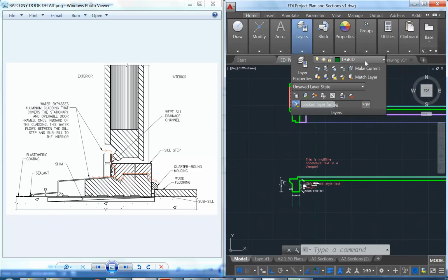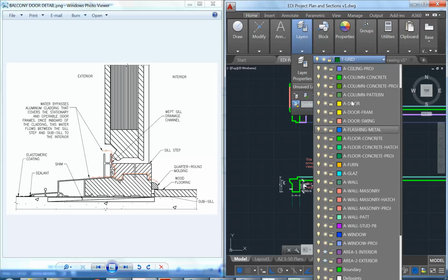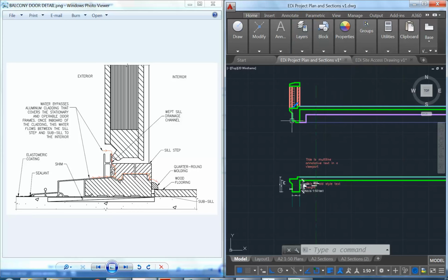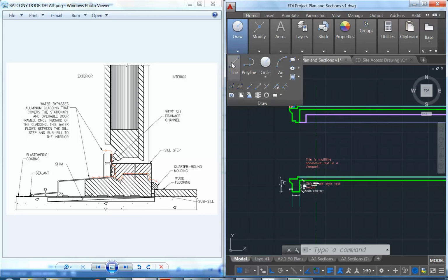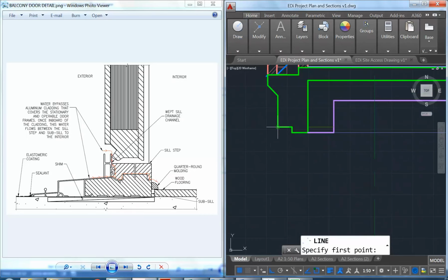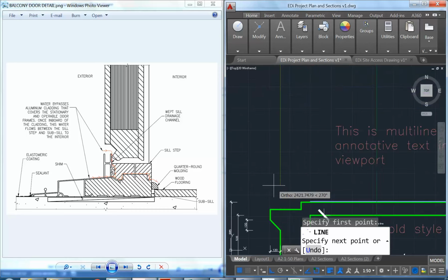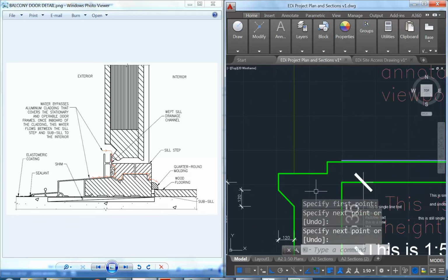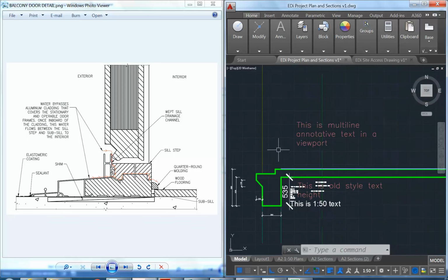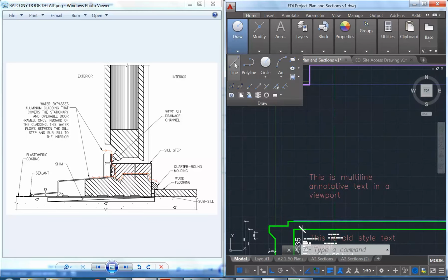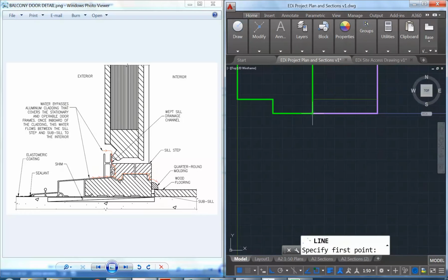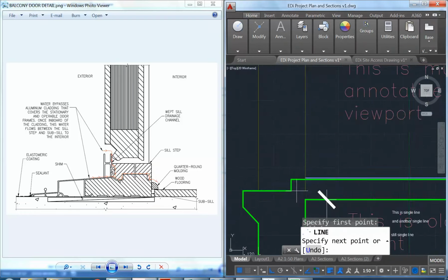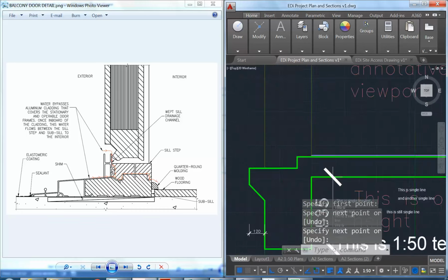And then it's probably not a bad idea to put in the lines projecting from the column, just so it's clear where the edge of that column is in section. So I'm just going to project a line down. Now we may do some sort of finishing there as well, where the slab sets down, depending on the balustrade detail, but worry about that later. And so for now I'm just going to draw another line on the other side of that column, projecting down again to show what the column looks like in elevation.